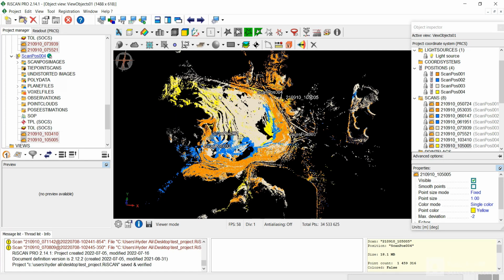So if I cut a thin strip that contains every scan position's data, how will we do it? We will go to this tool manager here and click on the option select mode, and then I will try to cut a strip in such a way that it encompasses some of the data from every scan. And after finishing my selection process, I will right click so that the selection process completes.